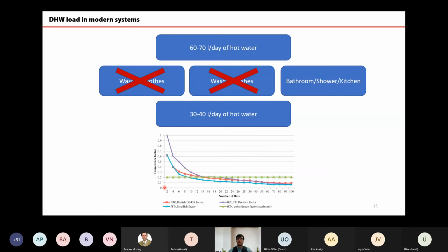So let's say if I take 35 kilowatt per one flat and I have 100 flats, that means capacity is 3,500 kilowatt, and this capacity I need to multiply by my coincidence factor, which is 0.1. So for 100 flats of consumers with one kitchen, one bathroom, I need approximately 350 kilowatt domestic hot water heat exchanger. So if you receive 500-600, that's of course a threat to stability of the system, and of course a threat to the lifetime of the heat exchanger.